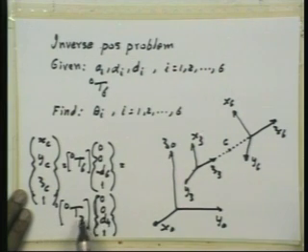What about this? This contains thetas. This contains the three thetas, theta 1, theta 2 and theta 3. So we cannot find it out numerically because we do not know the values of theta 1, theta 2 and theta 3. So when we multiply this, we get a 4-dimensional vector in which the first three elements are known as functions of theta 1, theta 2 and theta 3. Now if you equate those to the numerical values, we will be able to determine the unknowns theta 1, theta 2 and theta 3. So that is how we proceed.